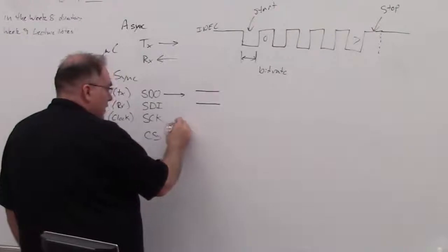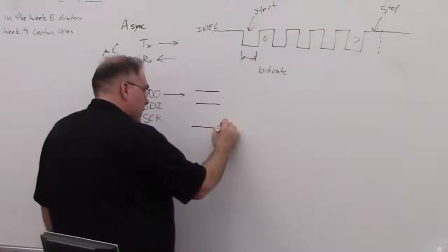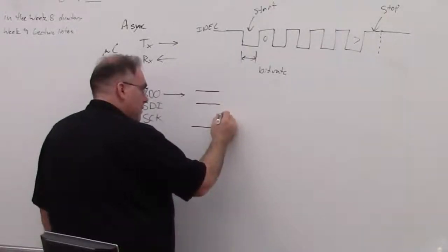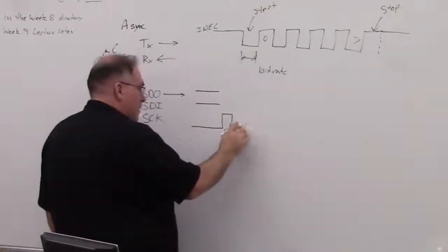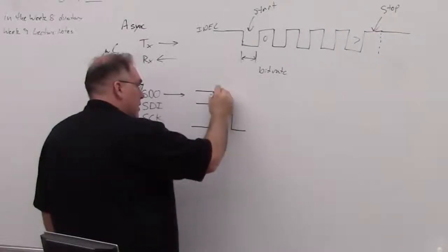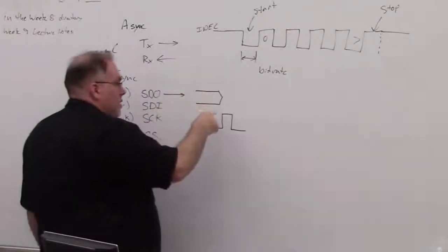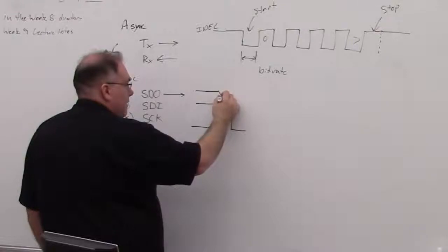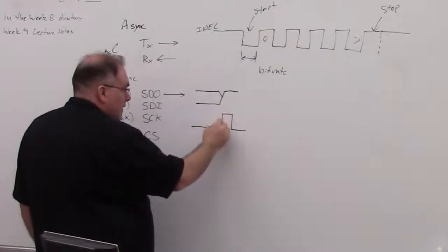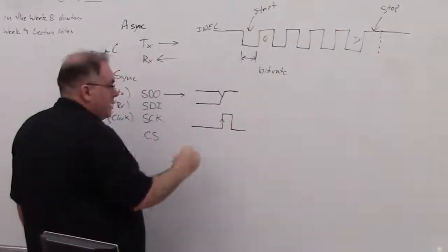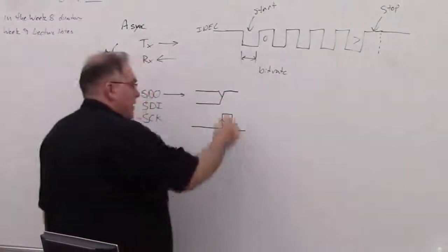And then when we're ready to start transmitting, we're going to have a clock that is going to possibly come high and then come low. And so when it transitions from high to low, or from low to high, our condition will come from this unknown state of either high or low to some known state, which may be, we'll say we're going high. And then the setup happens on the rising edge, and the data is read by the receiving chip, the DAC, on the falling edge.